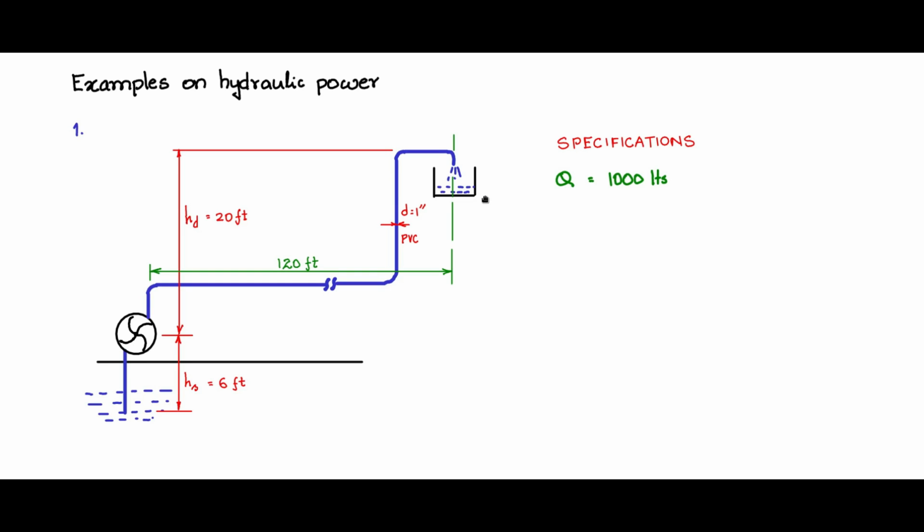Most of the pumps in our homes will be able to fill this up in 10 minutes time. So I will just put in some time here. The discharge time, delta T, is 10 minutes. So actually Q dot works out to be 1000 liters by 10 minutes, which is 100 liters per minute. That is the discharge rate or the flow rate.